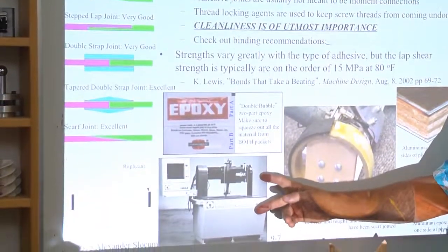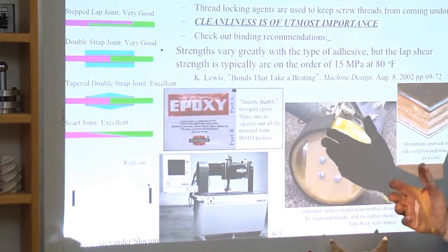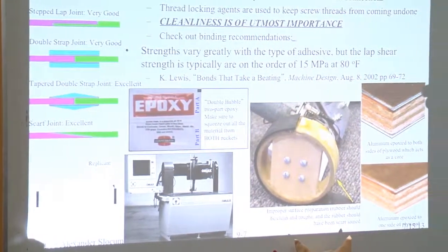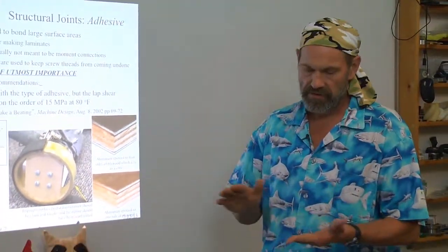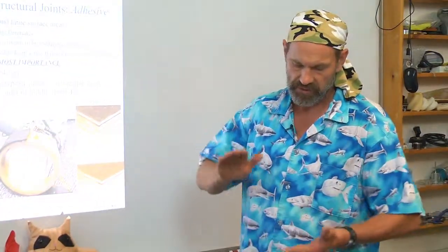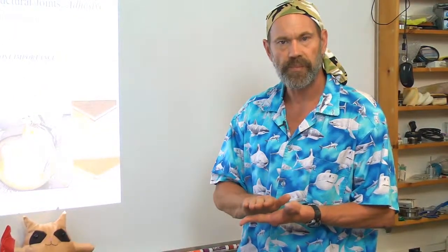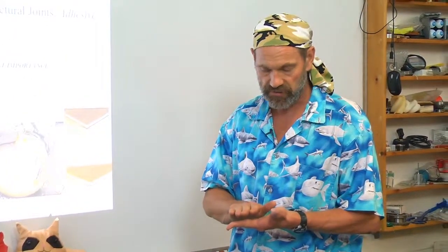Machine tools often make extensive use of adhesives between elements to hold them together so they don't have to be precisely machined. They can be good enough, brought together and glued together, but the positioning is then established with the fixture until the glue hardens. So I use adhesives in quite a lot of the machines and structures and products I design.